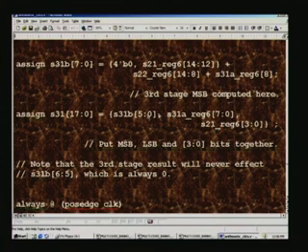So, all this put together will be the final multiplier output here, not yet registered. We put the MSB, LSB and the 3 to 0 bits together, that is what we have done here, and we had to note that the third stage result will never affect bits 6 through 5, which is always 0.